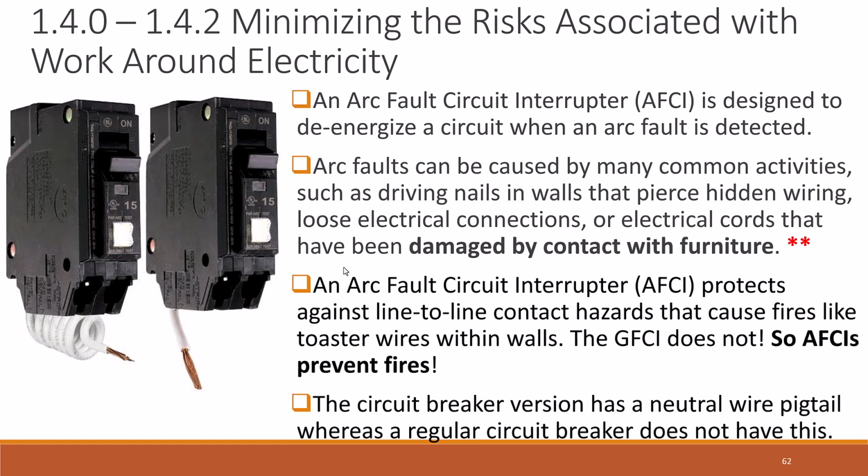Originally they were only used in bedrooms, and eventually they started adding them everywhere, because the AFCIs, the arc fault circuit interrupters, prevent fires. They prevent your cords heating up like toaster wires because they're sensitive enough to detect that behavior and trip.